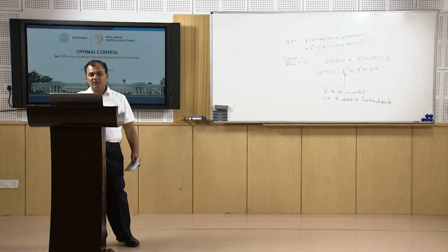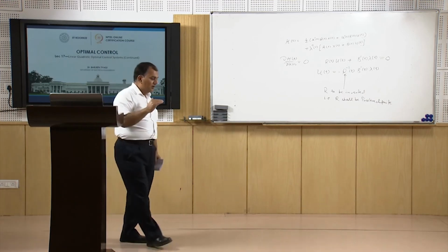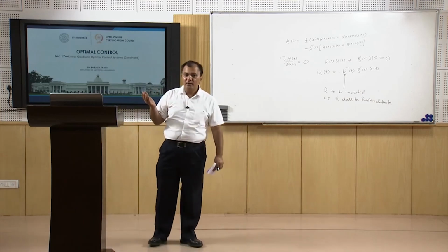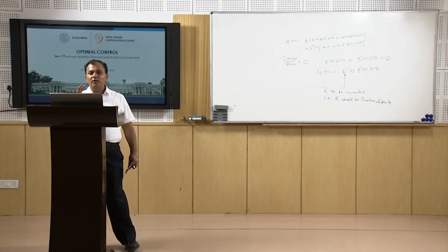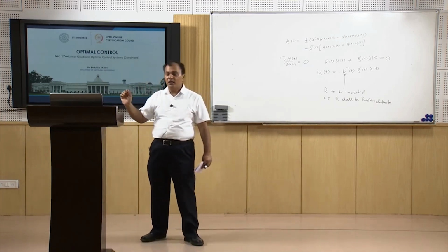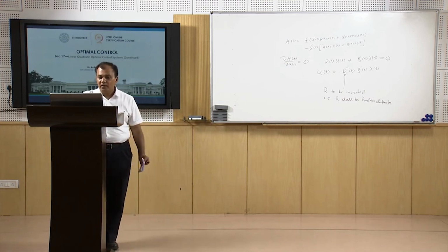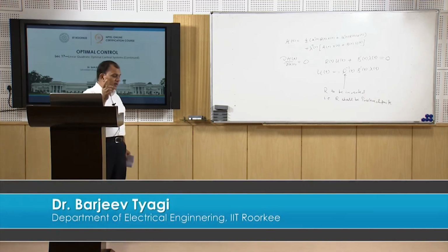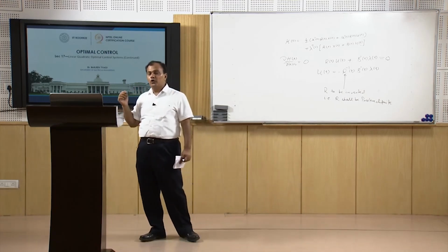So, whether my system is controllable or not, I can find some numerical value for all the states. So, for a finite time regulator particularly, it is not required for my system to be controllable, but in the later part, as my tf approaches infinity, then to get the solution my system must be a controllable system.